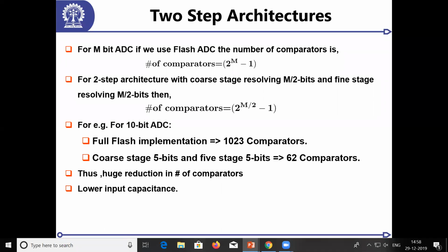N means the sample. So if I say that V in of N is the sample index, these are all sampled signals. Now this is a 2-input system, giving, let's say, 1-bit output. But I put a filter after this. I put a digital low pass filter and convert this into 16 bits. And that is what your CD does.